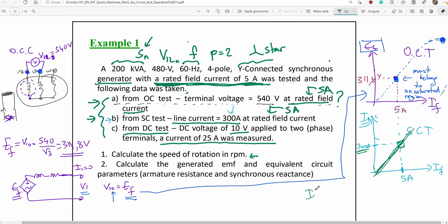So I squared R, the copper loss in the armature winding, will be crazy due to the large short circuit current and the square of that current. So the machine will burn out. It will be very dangerous, cannot be done, mustn't be done. So the saturated region is somewhere here, at a very far distance. So here's the point.